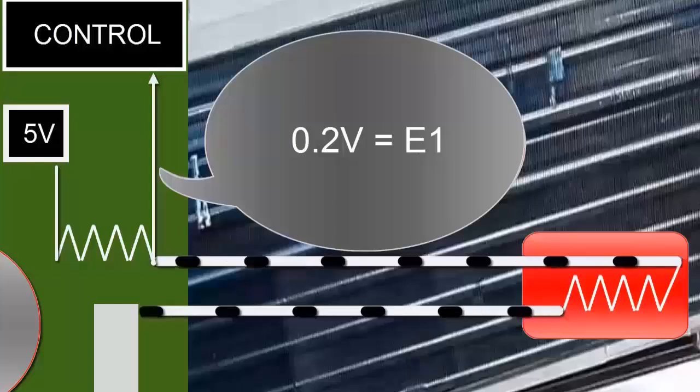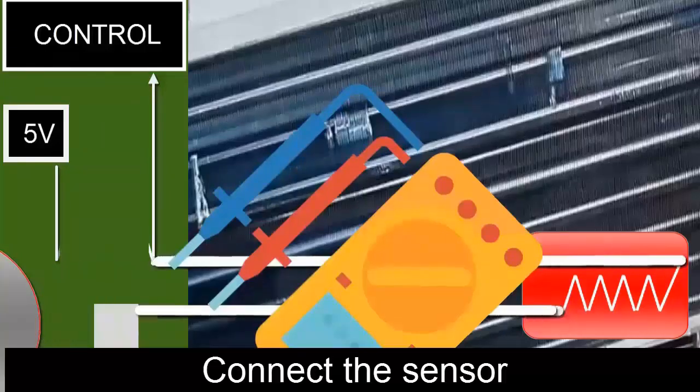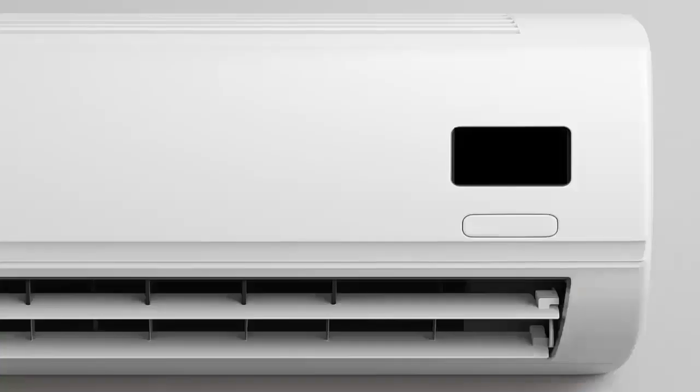F. Issues in the control board. Broken traces or damaged components may affect the sensor reading. Check the voltage at the sensor's power pins. It should be around 2.5 V if the board is energized.